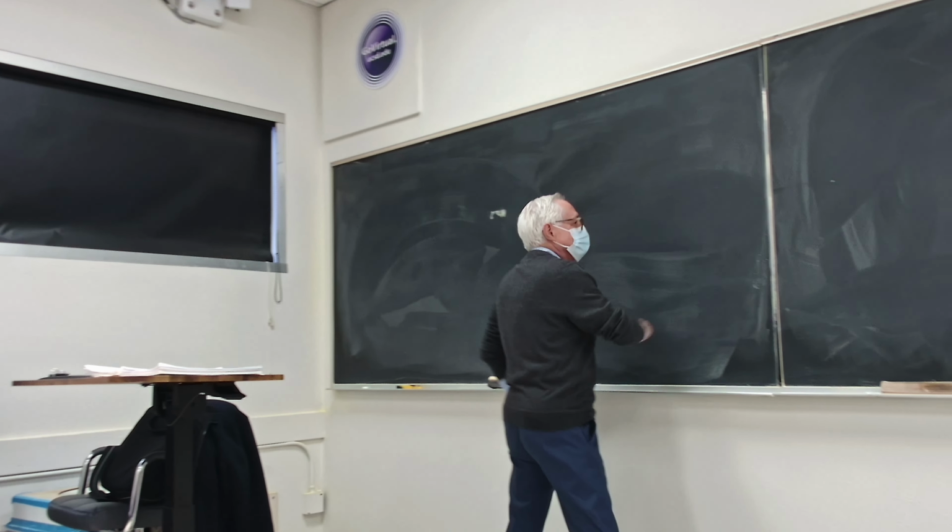State 1. T1, let's say, 800 Celsius, I don't know, I think the tables are given in Celsius, if I'm not wrong, right? P1, 15 bar. Fine. You go to the tables, you check, and you see that this for sure must be superheated.